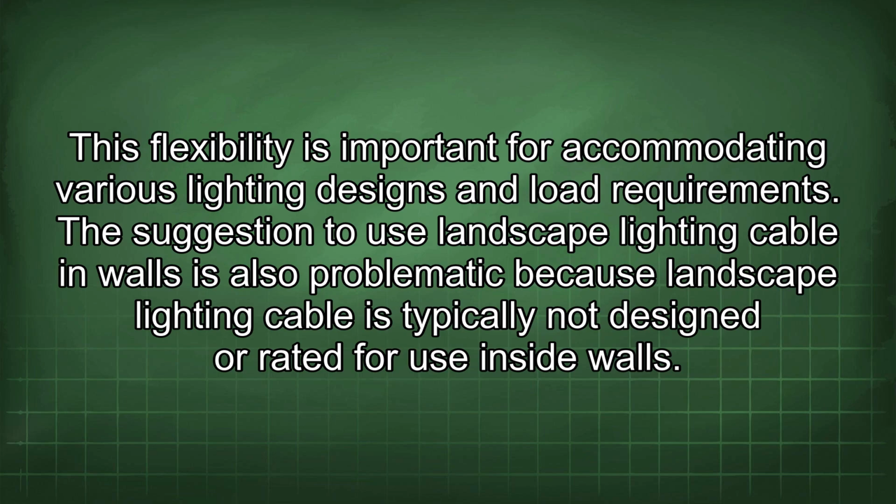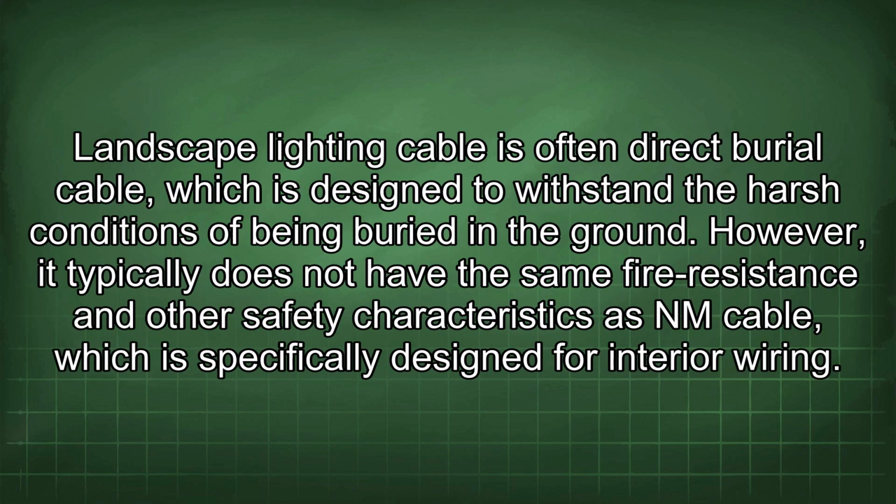The suggestion to use landscape lighting cable in walls is also problematic because landscape lighting cable is typically not designed or rated for use inside walls. Landscape lighting cable is often direct burial cable, which is designed to withstand the harsh conditions of being buried in the ground. However, it typically does not have the same fire resistance and other safety characteristics as NEC cable, which is specifically designed for interior wiring.